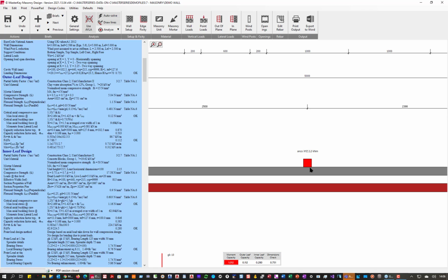Now the masonry guides on fixings will tell you that most shot fired fixings into the steel and mortared up will give you full fixity of your masonry. They're far stronger than the masonry was in the first place. So normally you assume it's just continuous rather than broken and simply supported.